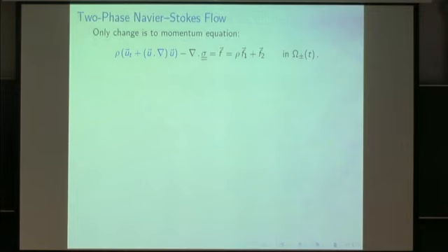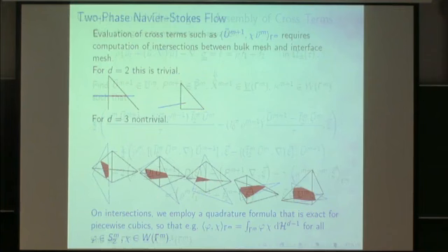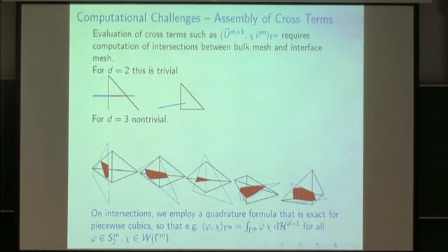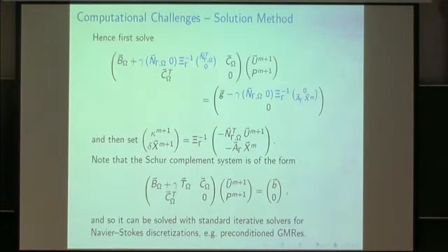Okay, I'm running short on time. So as I said before, you can do the same for Navier-Stokes, where you also have the convective terms in there. Then the scheme is a bit more complicated. We use this antisymmetric rewrite of the additional terms in Navier-Stokes, and you can get the stability proof across as before, and also the fact that you discover exact stationary states exactly like before. So I also won't discuss that much. It's just some numerical issues, what you have to do.